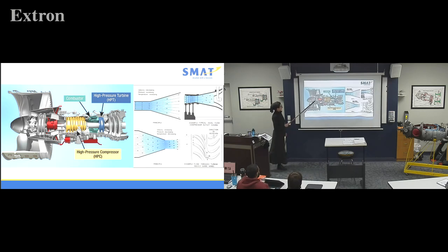And what is happening in these compressors? I want components and I want what's happening up there. So the rotor accelerates the air and the stator blades increase the pressure. Perfect. And what constitutes a stage of the compressor? Rotor stator. Very good.